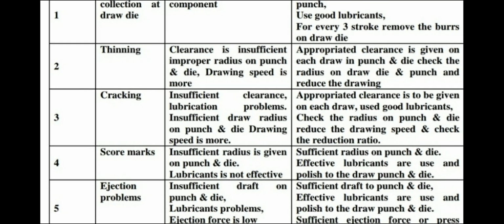So insufficient radius is given on punch and die, or lubricant is not effective, and the remedy is sufficient radius on punch and dies. Effective lubricants are used and the draw punch and die are polished.